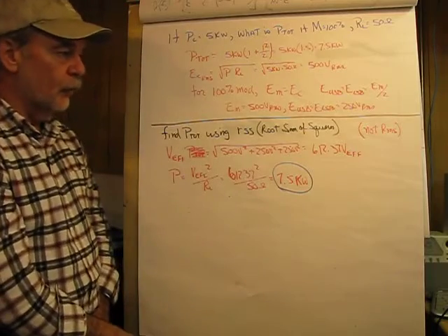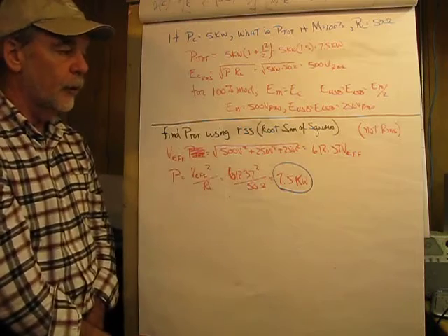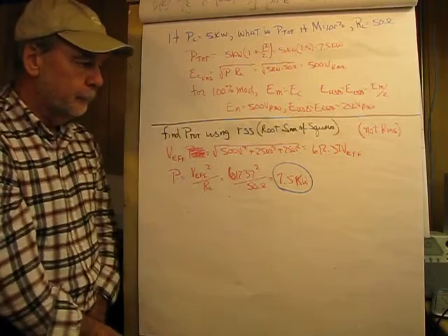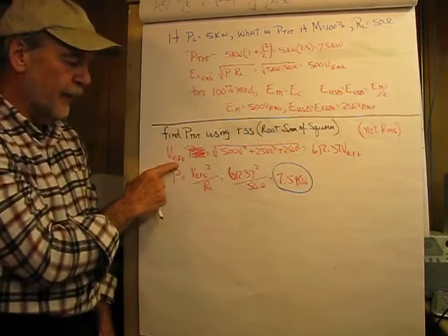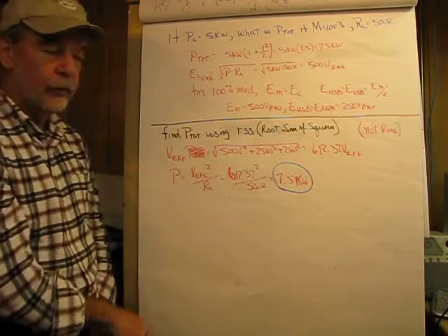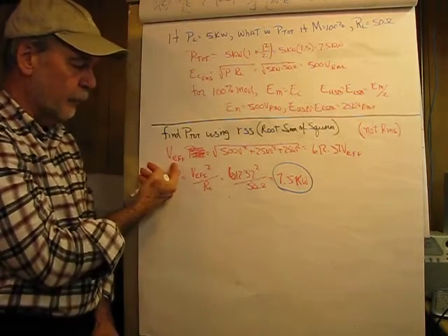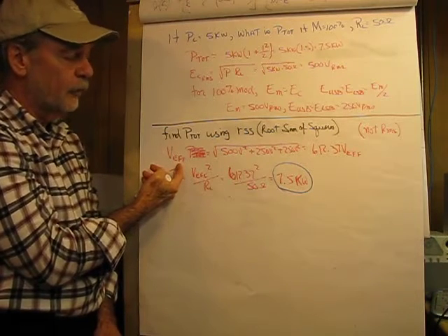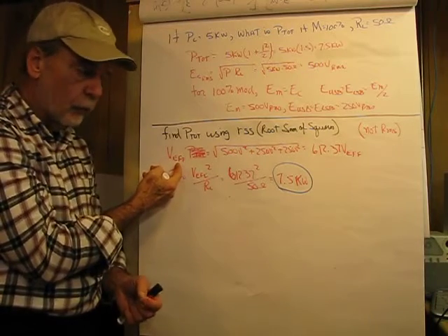So let's check the power using a different technique, and that's going to be the RSS, which stands for root sum of squares. This is finding V effective. Now this is not VRMS because there are going to be three components in this: the carrier, the upper and the lower sideband voltage, and what we want to find out is that power level, which in the above example would be 7.5 kW. What is the effective power expressed as a DC voltage?